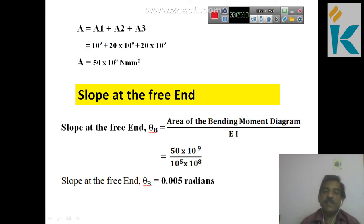So this is the A, we are going to use it in the formula for slope at the free end. So slope at the free end is theta B equal to area of the bending moment diagram divided by EI. So the area of the bending moment diagram is A, so 50 into 10 power 9 divided by EI, that is given in the problem, that is 10 power 5 into 10 power 8. So finally you got 0.005 radians. So this is the slope at the free end.